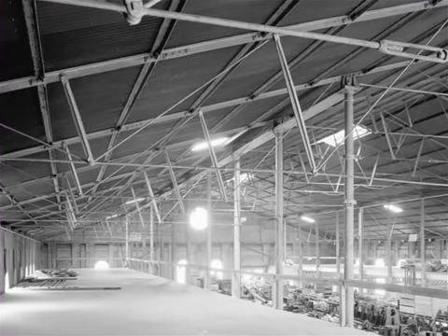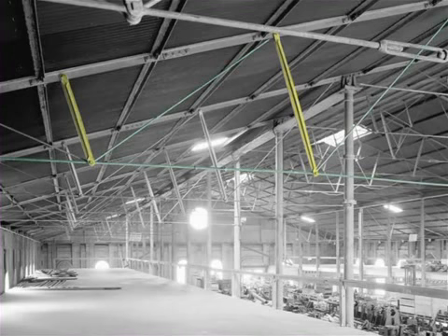Take a hard look. If you chose these two, you're absolutely correct. Based on the experiments we did earlier, it should be clear that these other members, the slender rods down below and these diagonals, must be tension members. They can't possibly be in compression because they're so thin. They'd buckle at a tiny level of load. But the two heavy struts were clearly designed to resist compression.